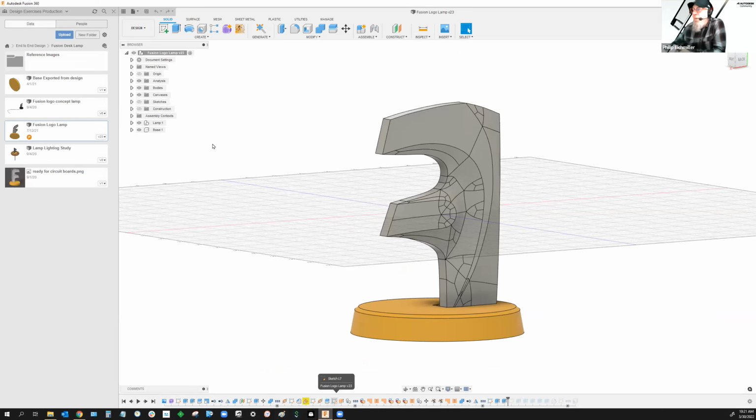Now, the way I want to answer that is, there's a lot of overlap conceptually, but in practice, it's crystal clear to me. I only use insert XREF for a specific workflow. This is not for building a bottom up, inside out kind of design. This is my traditional use from years of using Inventor, to consider XREF as standard components. So nuts, bolts, and screws sit on the shelf in my factory. I have part numbers for all of them.